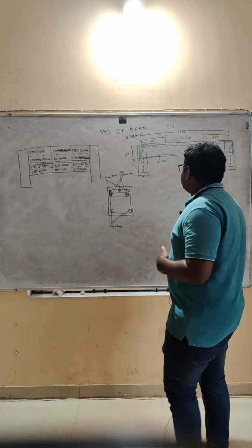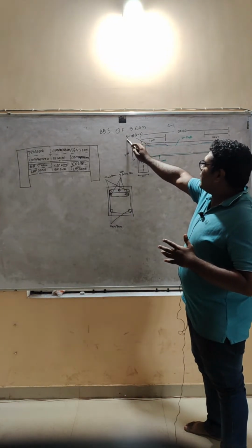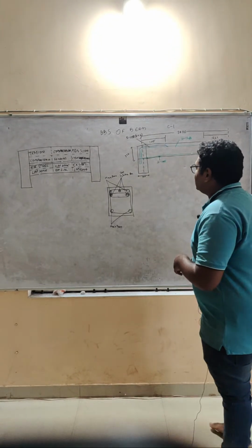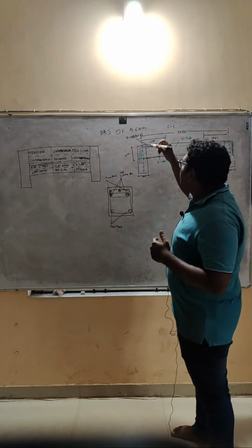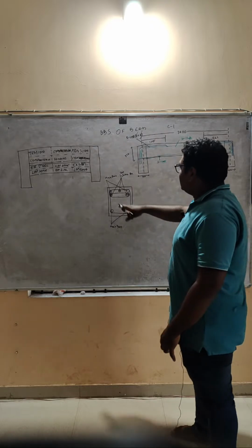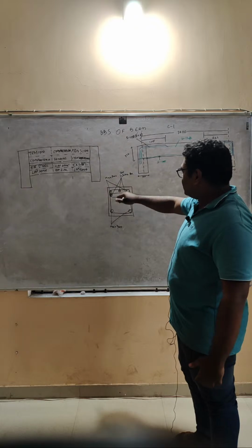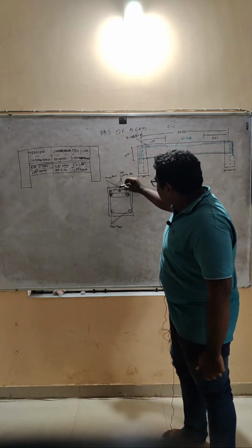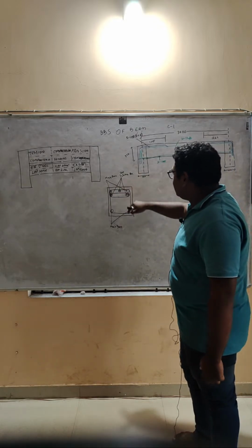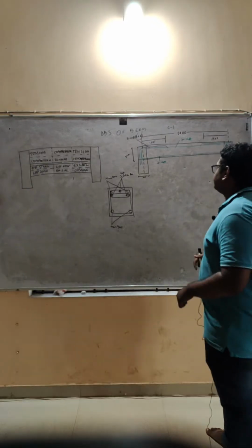Now let's proceed. For example, you can see that 5 rods of 12 mm dia are here, and this 3+2 denotation means 3 at the top and 2 at the bottom. So here you can see there are 3 rods at the top and 2 at the bottom. From these 3, two are the main bars, and one is the extra bar. Now we will proceed to our calculation.